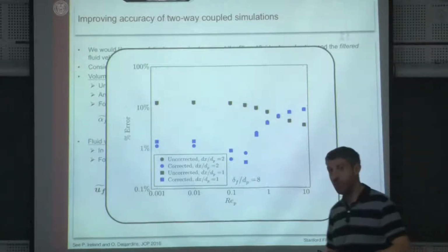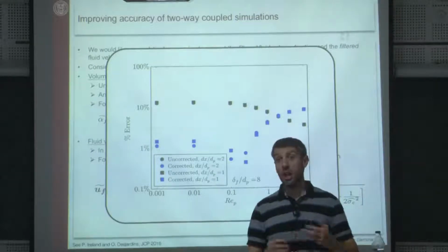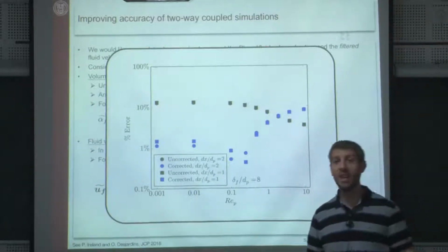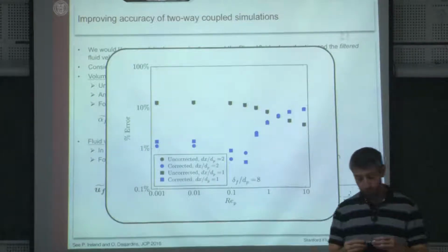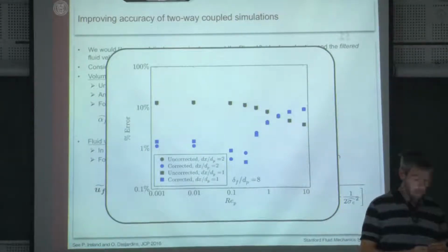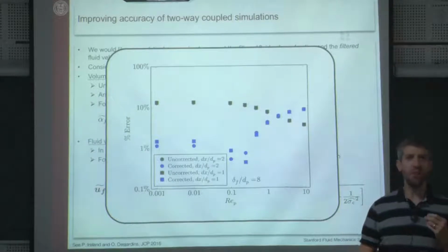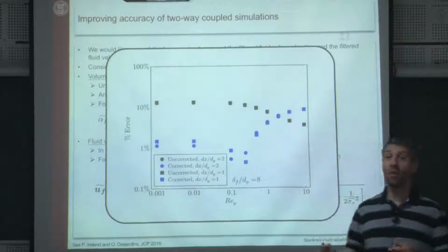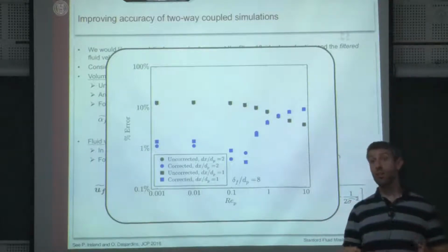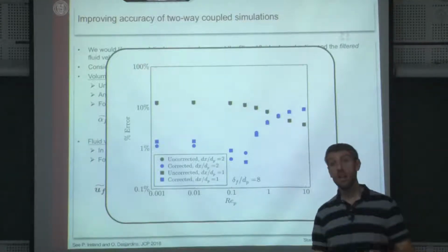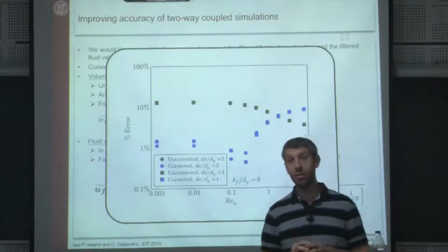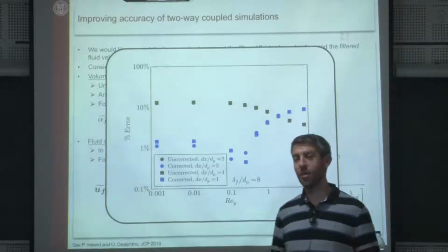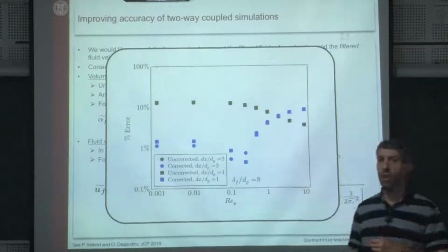As far as the volume fraction is concerned, none. It's a purely additive thing, so we can deal with multiple particles. As far as the velocity field is concerned, this is more of a problem. In the limit of low Reynolds number, the equations we're solving are linear, and so it is still an additive problem. So if we make the assumption that the Reynolds number is fairly low, we are still free to deal with single particles at a time. And that's as far as we've gone.